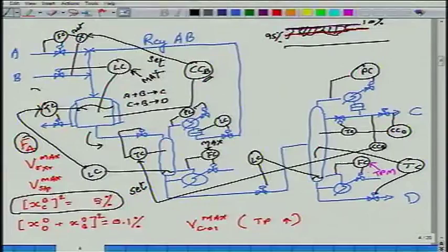XBC2 is equal to 5%. I am adjusting this set point so that the amount of C leaking down here is about 5%. Okay. And last but not least, which is not being done, well, that is actually getting done. I say that the amount of B leaking in the distillate, this guy, I set at some value, and then this guy is 0.1 minus whatever this is. Well, I can't write it, but you know, this set point is a dependent variable.